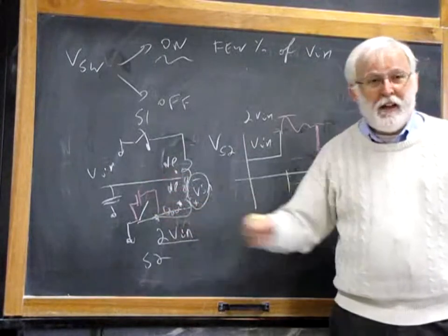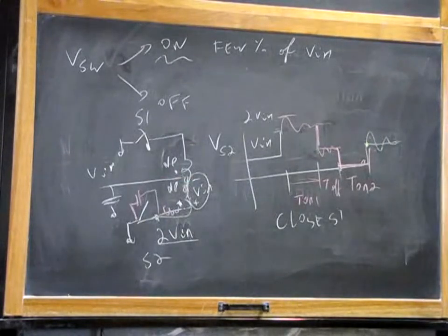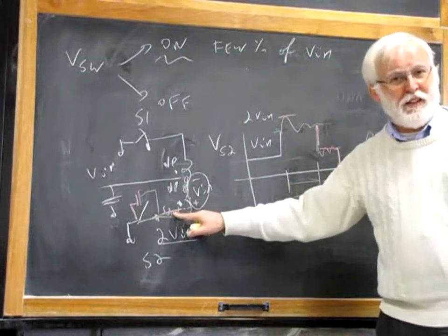When you open the switch on an inductance, what happens? The inductance gets mad, and it generates a very high voltage spike. Not 20-30% or usual rating, no, that goes very high, because here there is a very large current in this inductance.